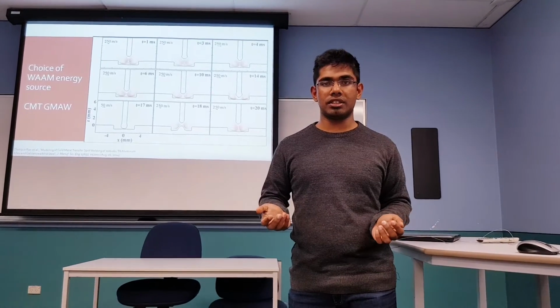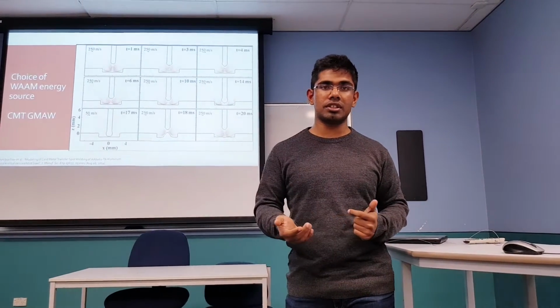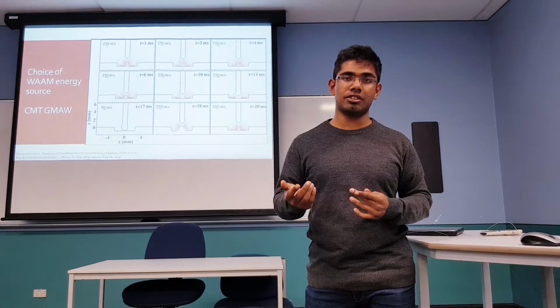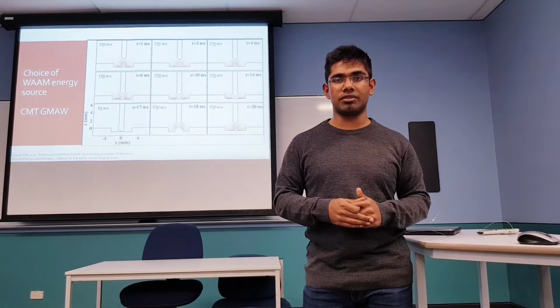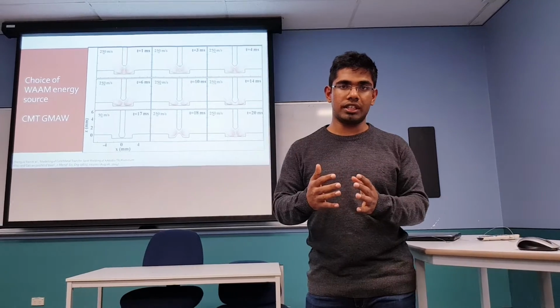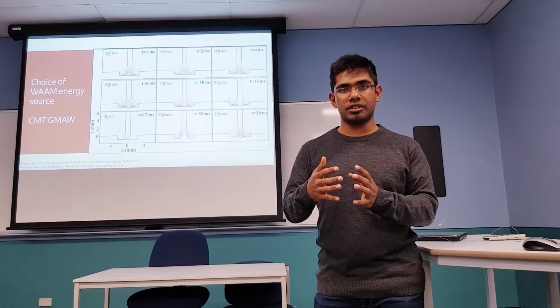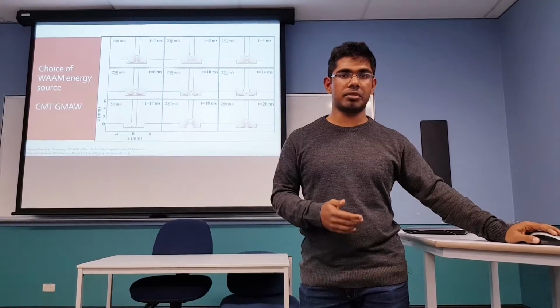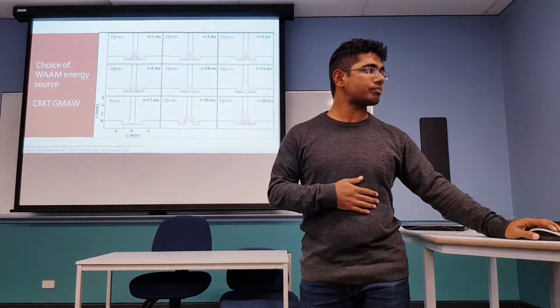However, it has several disadvantages in the form of poorer surface quality, which is improved upon by recent advances in the technology through the use of cold metal transfer technology, which involves a lower heat affected zone and lower temperatures generated at the torch, so therefore the surface quality is greater and very little spatter takes place.